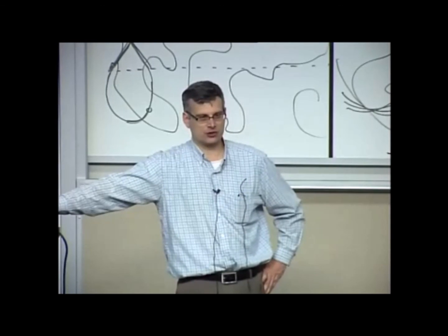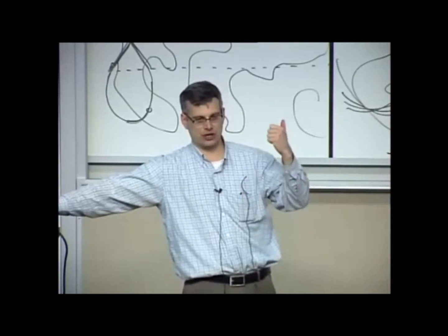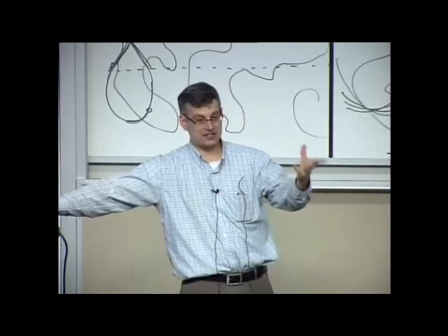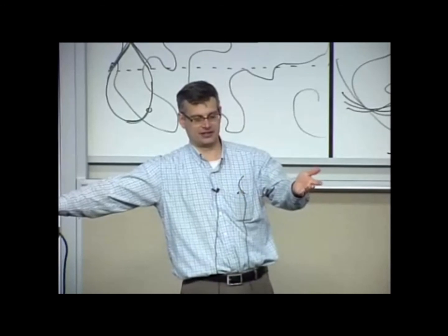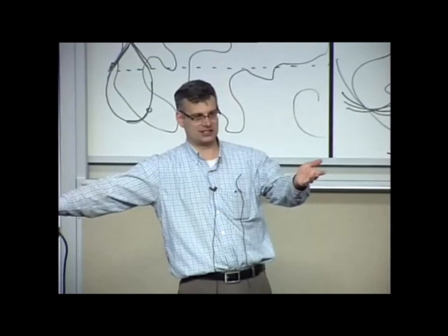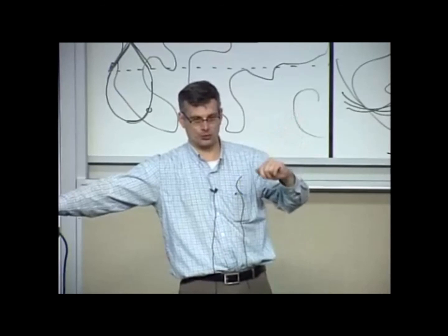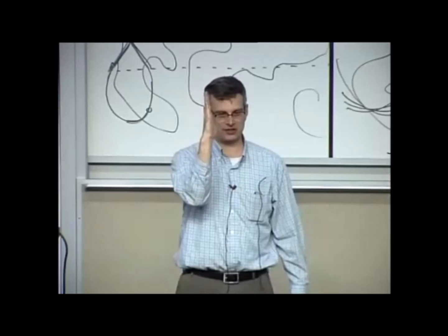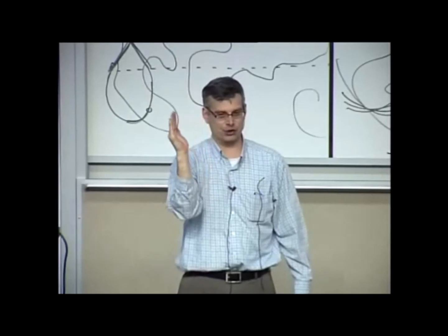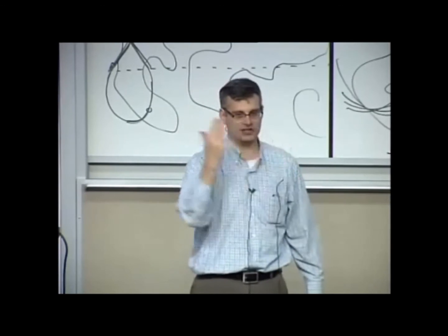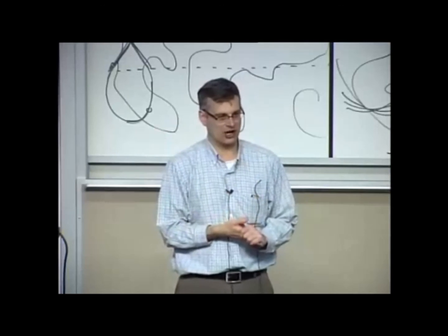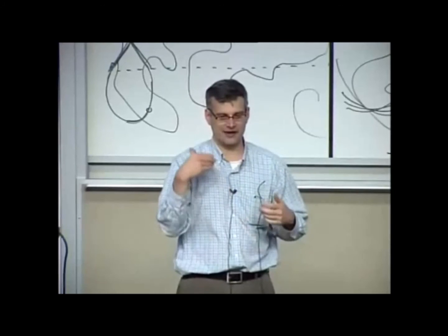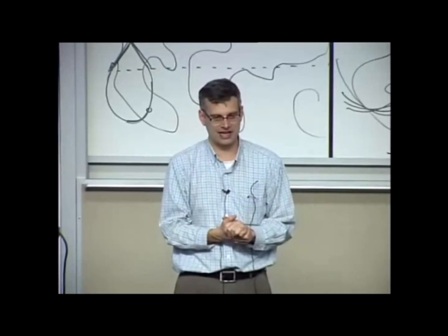So you got to put it in the right orbit with the right eccentricity, the right period, and then you also have to do it with the right inclination, and you have to time it right too, so that if you're doing this Sirius Tundra orbit, your median longitude is somewhere centered on North America, and you didn't accidentally put it over the Pacific Ocean or the Atlantic Ocean. So there's a lot to get right in the timing of when you launch and how you launch it, and what kind of final coordinates you give its velocity and position.